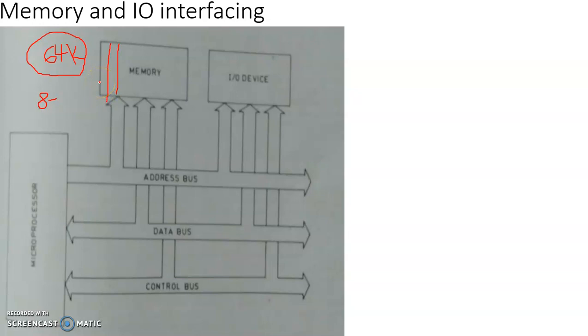So sometimes you require 8 kilobytes of ROM, another 8 kilobytes of programmable read-only memory, yet another 8 kilobytes of erasable programmable read-only memory, and the remaining 8 kilobyte units of memory happen to be the random access memory locations. So generally memory will be an assembly of different types of memory elements.